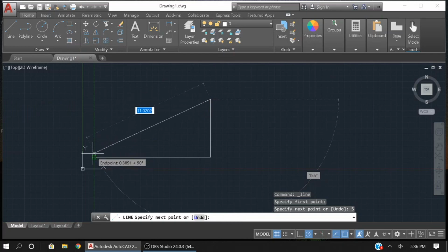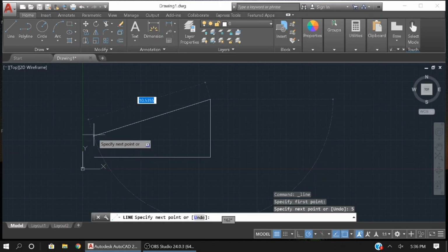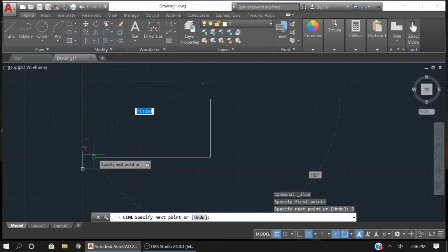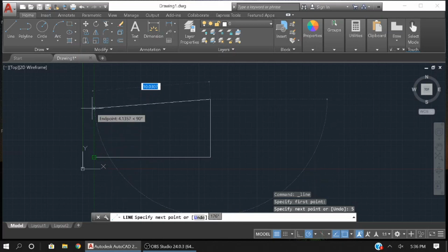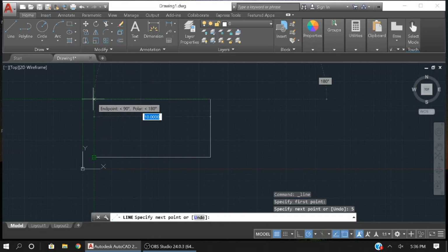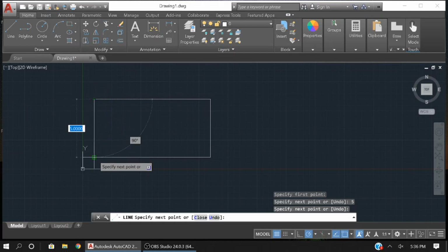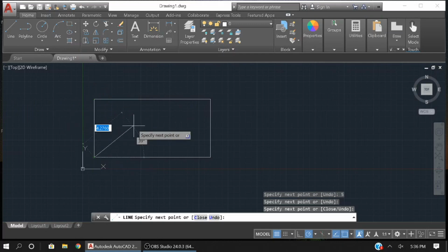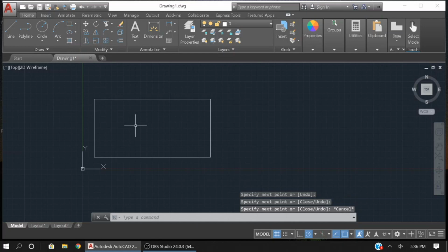I come on that endpoint, and I move my mouse up. Okay, just didn't grab it. Okay, now it did. Perfect. As soon as I hit 90, it automatically locks for me, right? I can move around a little bit, but it won't do anything, which is very good. I'm just gonna click here, and then click on the endpoint, right? So now I basically made a triangle.